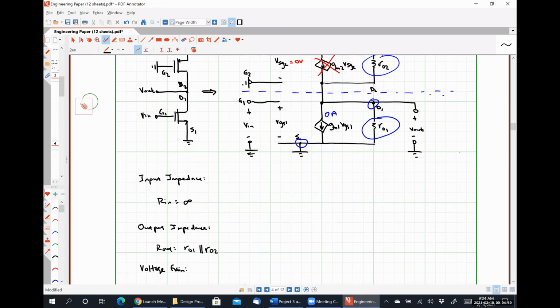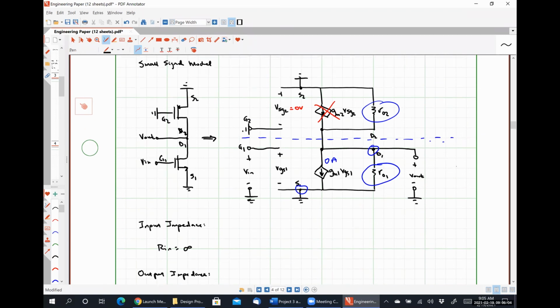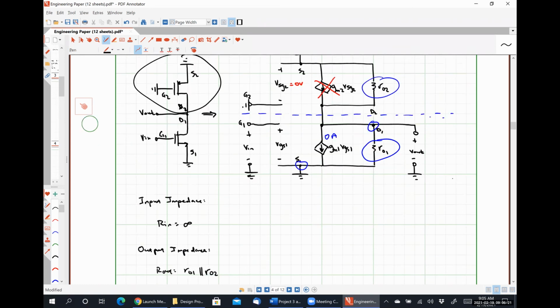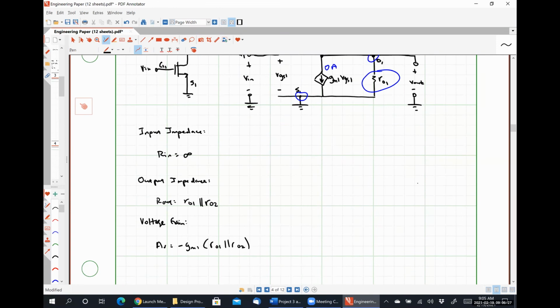So really all that we've done between the previous example and this example is we're using this MOSFET PMOS transistor to replace that resistance RD with a significantly larger value resistance, small signal resistance, which should therefore increase our voltage gain appreciably, but we won't run into the issues of dipping into the triode region with a well-selected bias voltage VB.